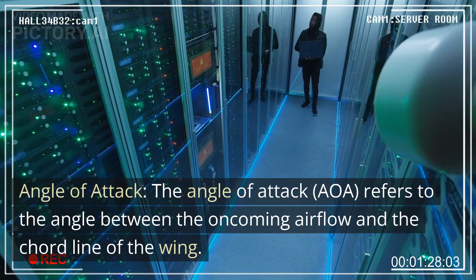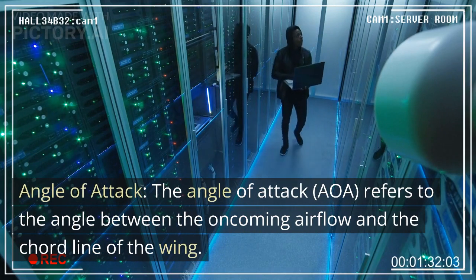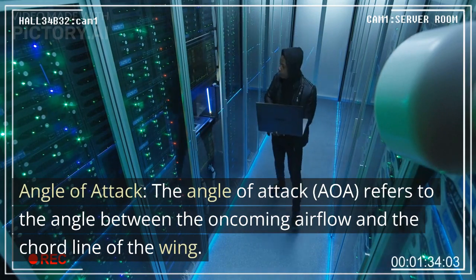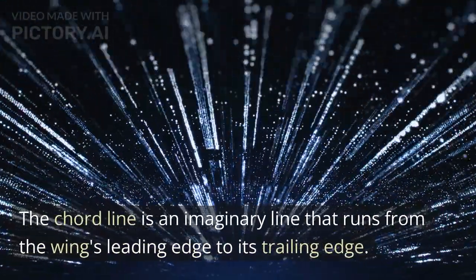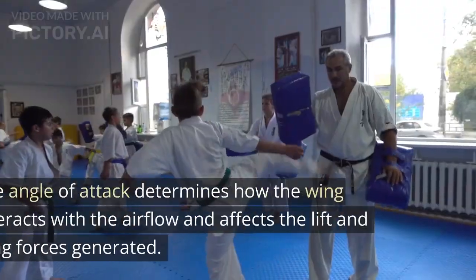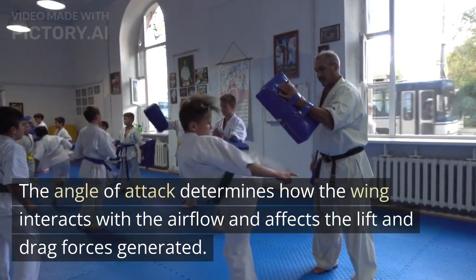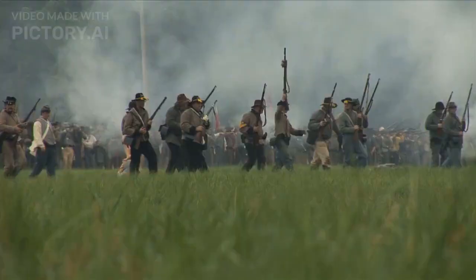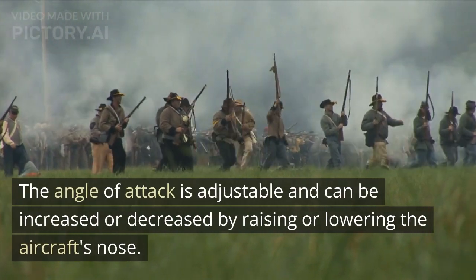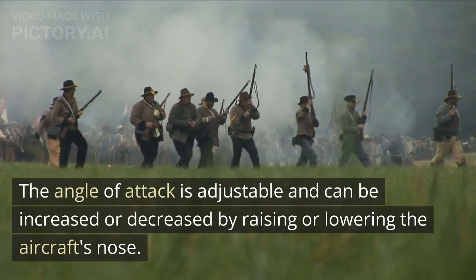Angle of attack. The angle of attack, AOA, refers to the angle between the oncoming airflow and the chord line of the wing. The chord line is an imaginary line that runs from the wing's leading edge to its trailing edge. The angle of attack determines how the wing interacts with the airflow and affects the lift and drag forces generated. The angle of attack is adjustable and can be increased or decreased by raising or lowering the aircraft's nose.